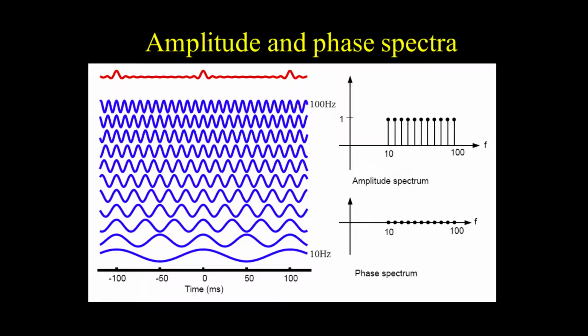These results, and those shown in the previous slide, suggest that the process of reconstructing a periodic time signal can be performed by adding individual cosine waves in the form of a series in which each cosine wave has its own frequency, amplitude, and phase. Our next objective is to demonstrate that this observation is correct. Any periodic signal can be decomposed as a sum of cosine waves. This sum is known as the Fourier series.